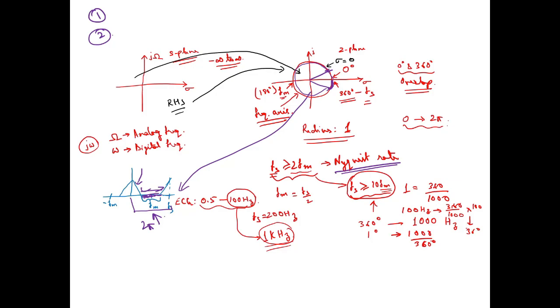One example is, suppose you want to look into the frequency spectra of the signal. So what happens in DFT? If you are having only 4 point signal components, you'll be getting a 4 point DFT. But if you sample it to say 16 points, you will be getting frequency components for the 16 points. So you will be able to see the frequency axis in a much better way.